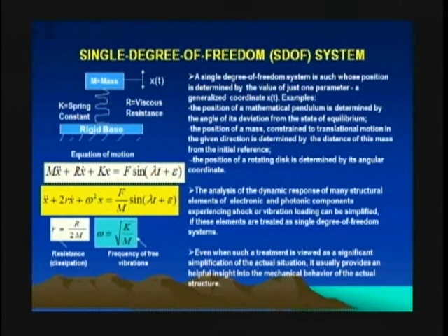So that's why people use, as at least a first useful approximation, viscous damping, because in many cases it reflects the actual situation, but most importantly it helps you come up with a linear differential equation, and based on that understand the physics of what's going on.